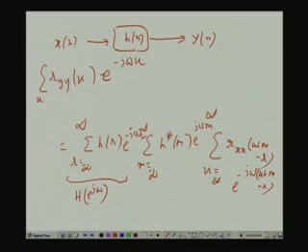Second quantity you can take the star out. So, e to the power minus j omega m it becomes. Okay. You can easily see that this is nothing but h star e to the power j omega, and here k plus m minus r can be called k1, everything else remains same. So, this is the DTFT, discrete time Fourier transform, of r_xx[k'] rather, which is the input power spectral density, which is phi_xx e to the power j omega.